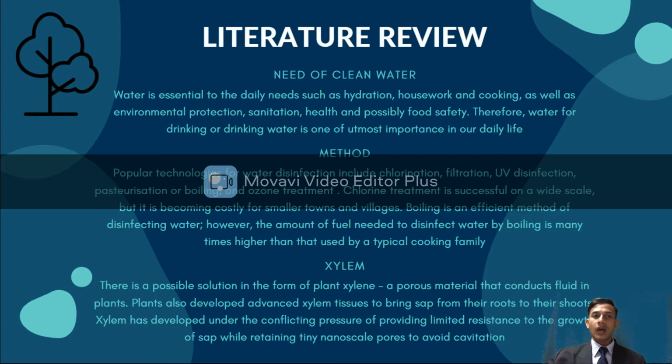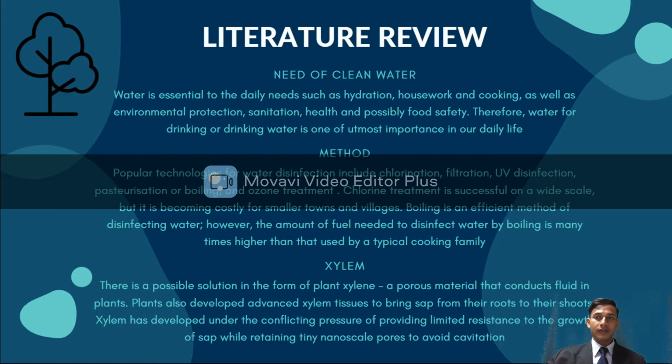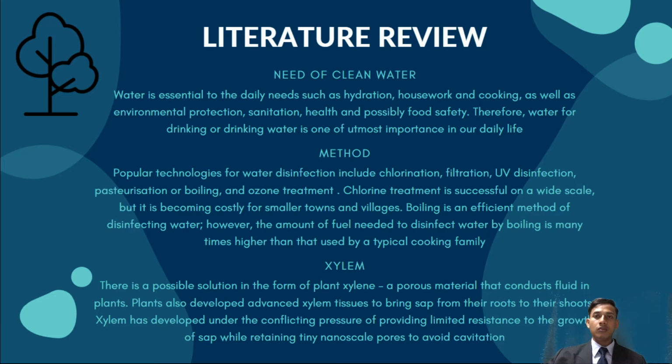In terms of method, there are many popular technologies for water disinfection, including chlorination, filtration, UV disinfection, pasteurizing or boiling, and ozone treatment. Chlorine treatment is successful on a wide scale, but it is becoming costly for smaller towns and villages. Boiling is an efficient method of disinfecting water. However, the amount of fuel needed to disinfect water by boiling is many times higher than that used by a typical cooking family.